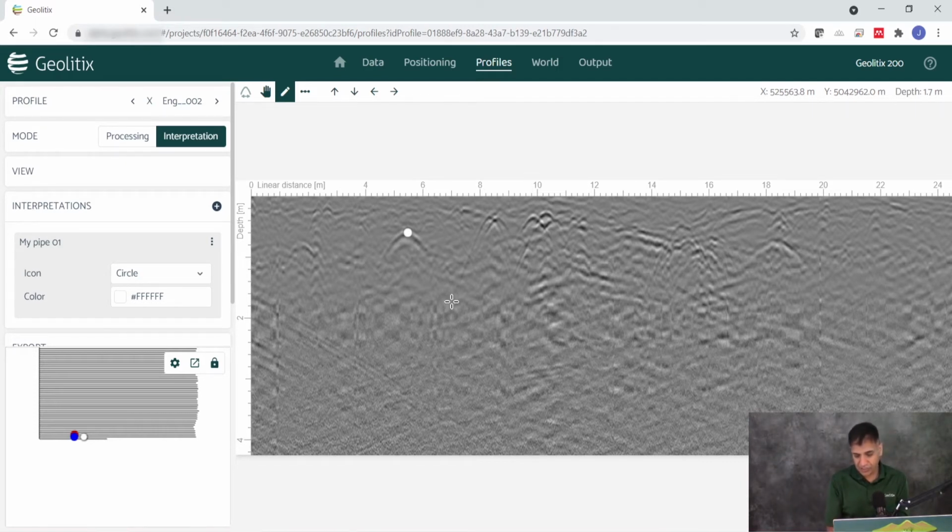And in many jurisdictions, that's not the legal way of doing it, particularly in places like the UK, which is leading the world with its PAS 128. It needs to be documented to a specific level of accuracy and confidence. And some states in the United States are like that, as well as Australia. So we're seeing a shift away from just spray painting on the ground to actually capturing data in a proper, systematic way, and going back to the office and processing it and delivering AutoCAD files or deliverables beyond just a can of spray paint.